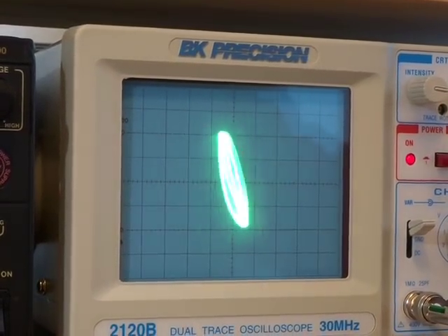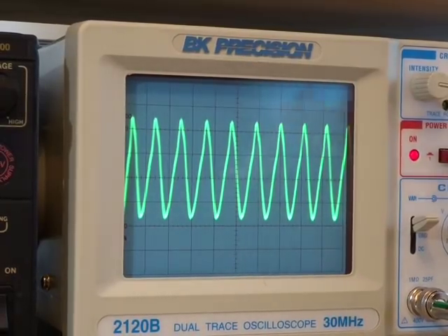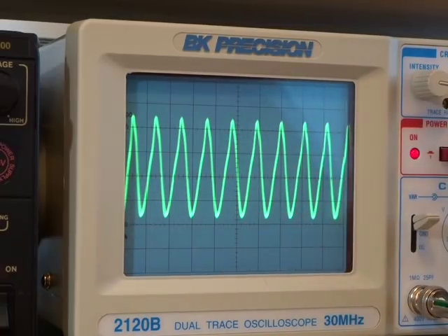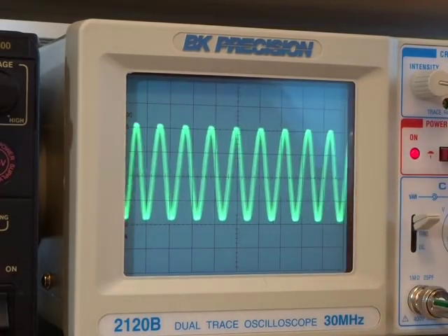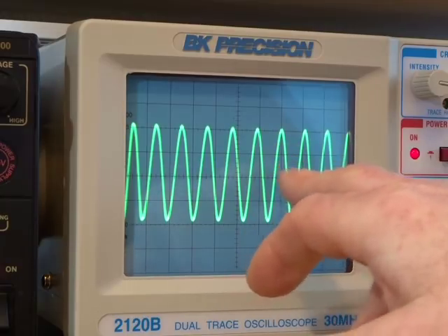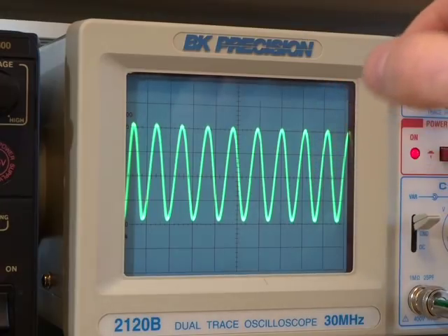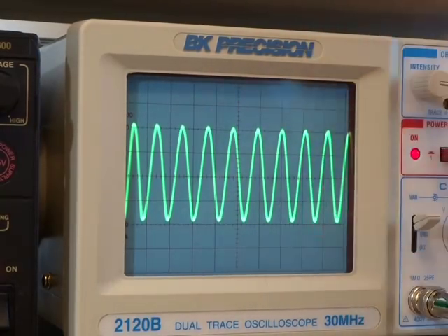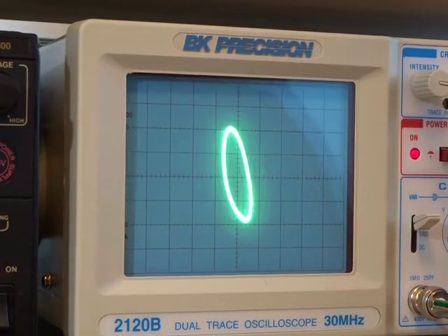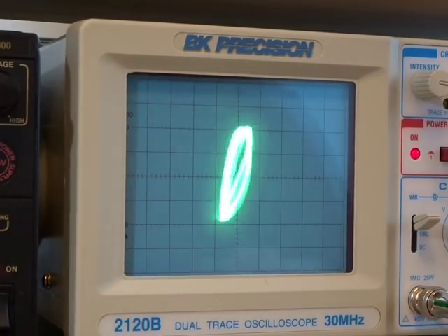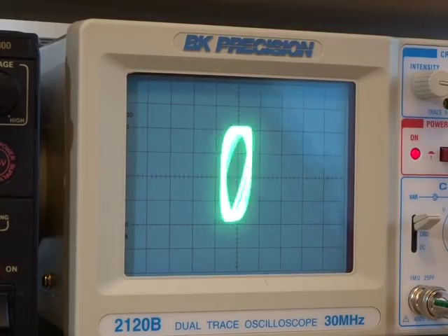So if we go to channel 1, let's take it off that mode there. Channel 1 is the output of the crystal oscillator, and channel 2 is the output of the signal generator, and I'll just trigger off 2. And I've adjusted the amplitude or the magnitude of the signal generator to give me the same amplitude between the 2 inputs. Now if I go to X and Y mode, trigger off that one, I can then start to create the phase symbol here, and I won't pronounce the French name because I'll get it wrong.